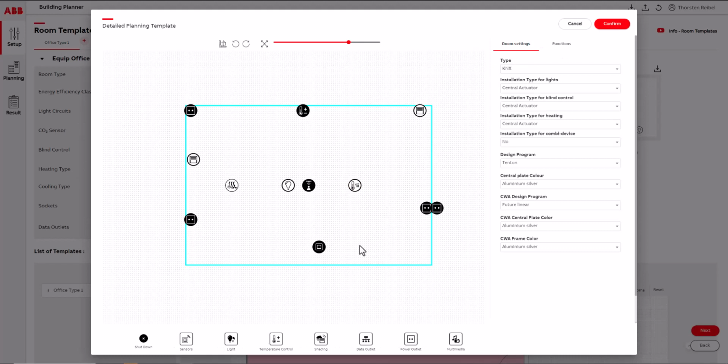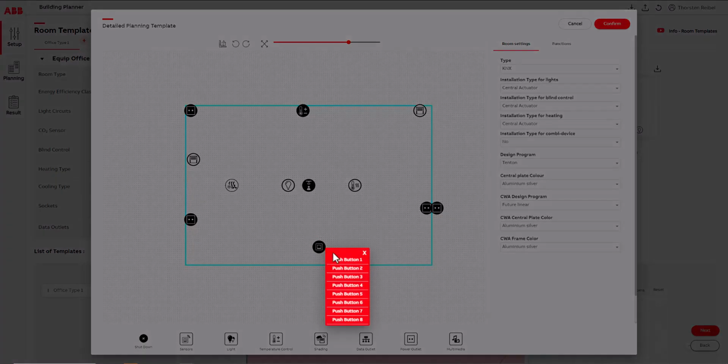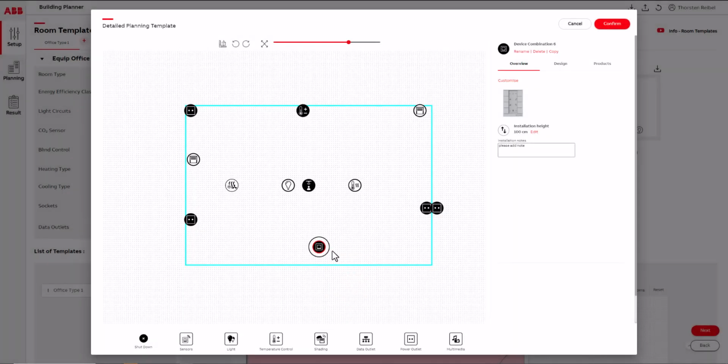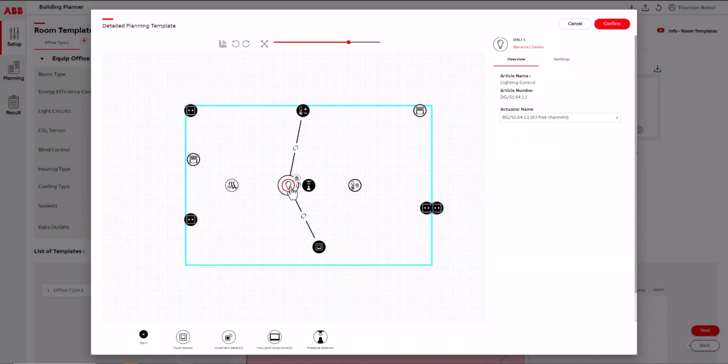If it is an element with channels, e.g. a rocker or a push button sensor, click on this channel, select the load circuit, e.g. light, and thus functionally connect them via connecting line. Advantage: the installer, who later configures and programs the KNX devices with the ETS, receives the relevant information. You can delete it again by clicking on the magnet in the connection line.